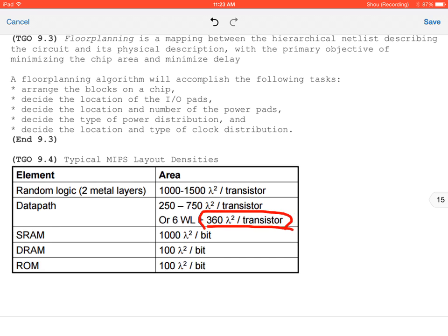This is the constant we used to help calculate our IV curves, to be able to calculate the sizing for PMOS and NMOS. You recall that we calculated the actual amount of current? And in order to do that, you had to calculate this number. So that wasn't just busy work. These all are meant to tie together. If you look back at your problem, you'll see that 360 was a number you calculated.